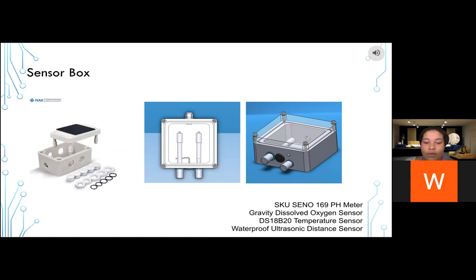Thus, each of the hole cutouts along the bottom-facing edge of the box are surrounded by a rubber ring to provide a seal and prevent water infiltration. The sensor cables then exit the box through a hole on the top sealed by a PG9 cable gland. Finally, the box lid is screwed to the top, and a rectangular cutout along the top face of the box aligns with extrusions on the lid to create yet another seal.